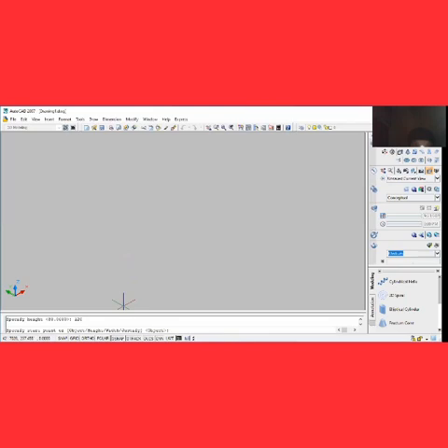If you want to change the width, you can also type W and then enter. Now let's choose a width of 50 and then enter. So now the start point, let's choose this place as our starting point. You can see that it's different from the first one we drew. You can take it to any point that you want.